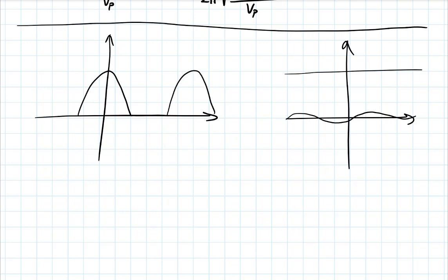Now that signal, you might say, has some average value plus some large variations. You can think of it as having two components. One average constant value plus something that has a lot of variation. I have turned that into something that does have the average plus very small variations. I have filtered out most of the variations. The component that was varying with time, I have gotten rid of a big part of it.